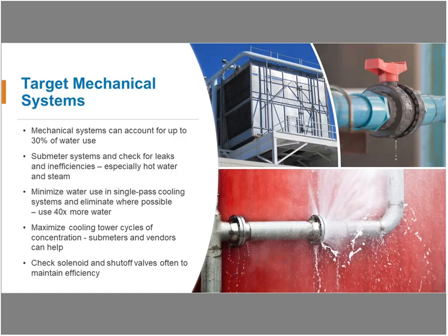The other thing to look at is, because valves can leak, or because of wear and tear, we encourage people to check your solenoid and shut-off valves often. If they're not cutting off cleanly or not cutting off as expected, it can be a huge amount of water wasted. So those are some things to look for, at least in the mechanical section of your facility.